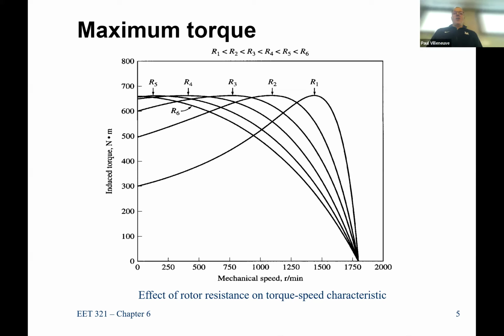They all have the same peak torque, right? So there's no advantage to doing it. Pay less current? No. Because if they use less resistance, maybe use less current. So if you inject resistance in there, obviously you're going to have more I squared R losses, right? Any other reason?